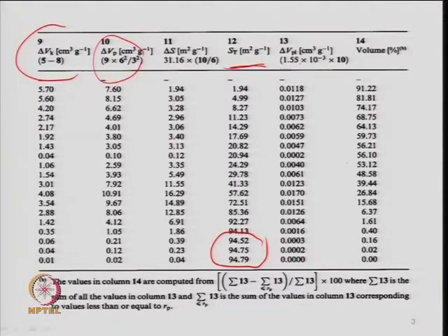Then there is some additional information: this delta V_P L is corrected, because you calculated it at the adsorbed condition, and you can convert it into STP conditions. So, just correlate it with the density of the gas and the density of the liquid. This is the ratio of the density of the nitrogen gas divided by the density of the liquid nitrogen, right. That will give you nothing but the volume at standard condition. And finally, this is your cumulative pore volume, right.